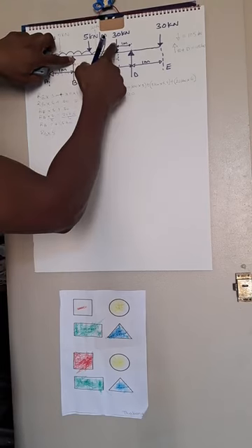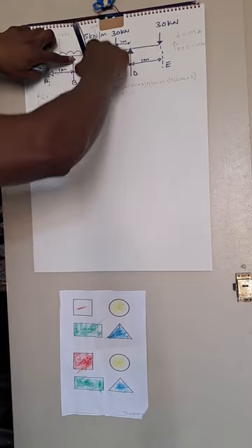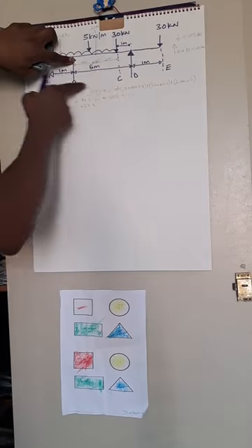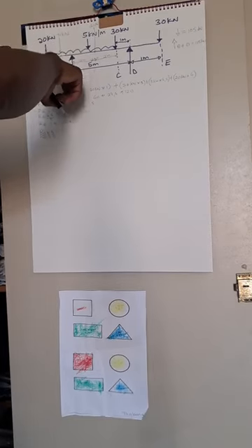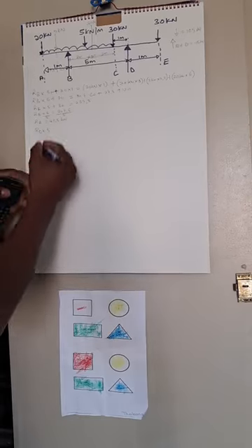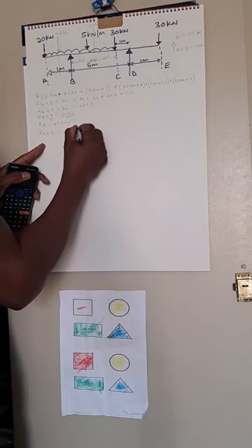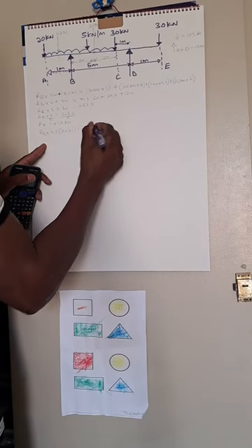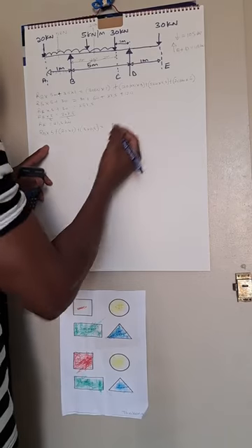But these 3 forces are going to point B in a clockwise direction. You can see this one comes here clockwise, this one comes here clockwise, same applies, comes here clockwise. But 5 times 0.5 goes here anti-clockwise, 20 times 1 goes here anti-clockwise. So we say plus 20 times 1 plus 5 times 0.5. So anti-clockwise moments equals our clockwise.